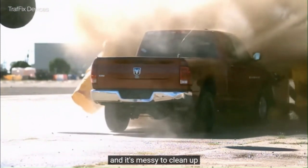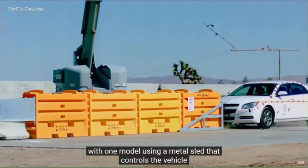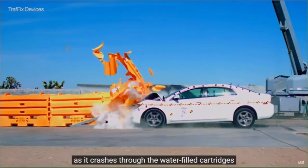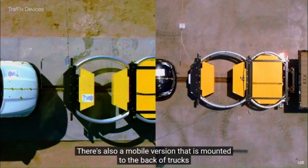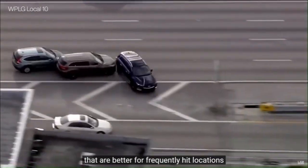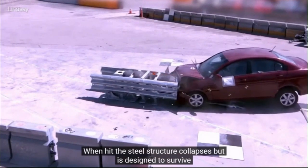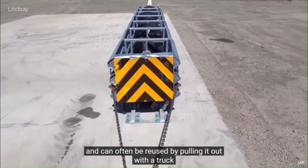These are also useful for construction sites, with one model using a metal sled that controls the vehicle as it crashes through the water-filled cartridges. There's also a mobile version that is mounted to the back of trucks that are used to protect road crews. Next, we have cushions like this Quad Guard M10 that are better for frequently hit locations. When hit, the steel structure collapses, but is designed to survive, and can often be reused by pulling it out with a truck.